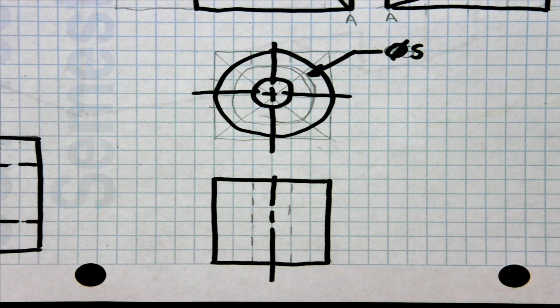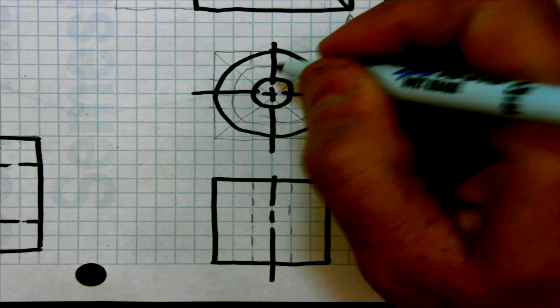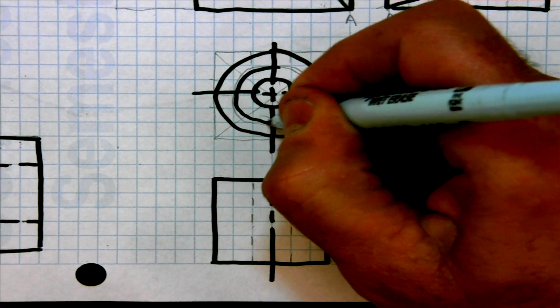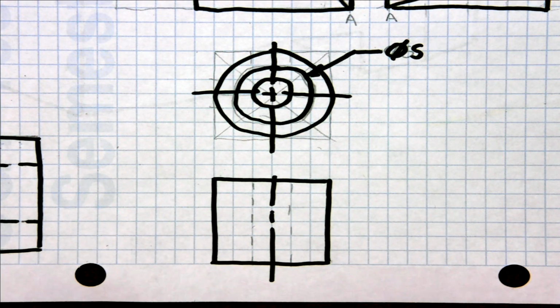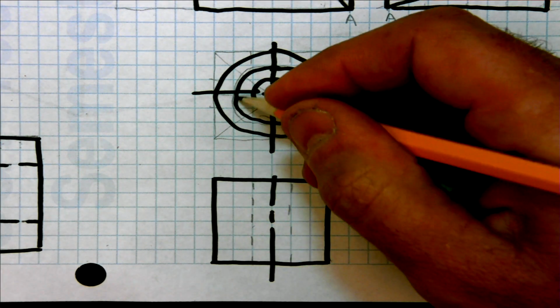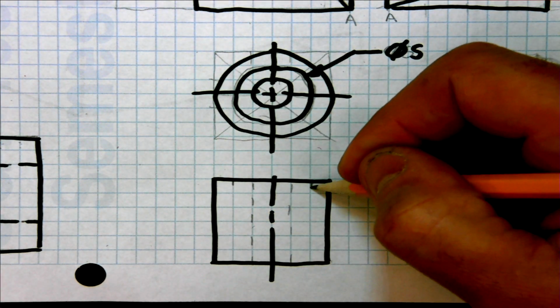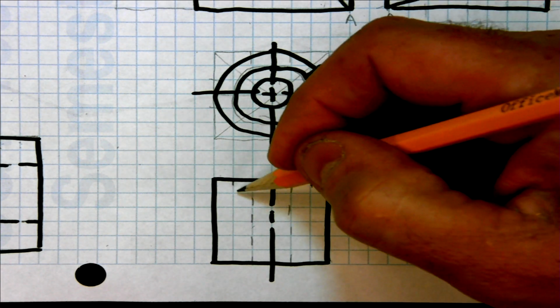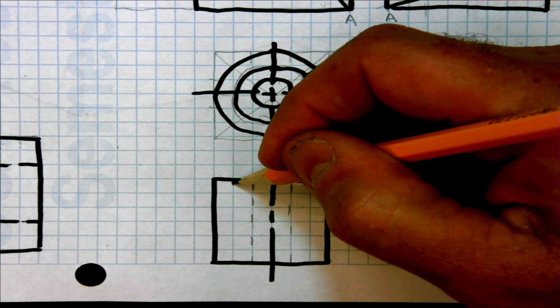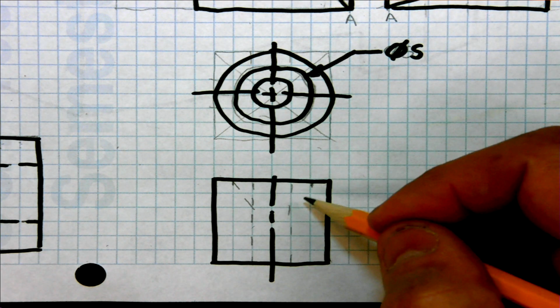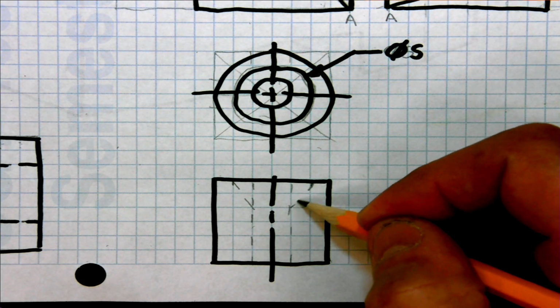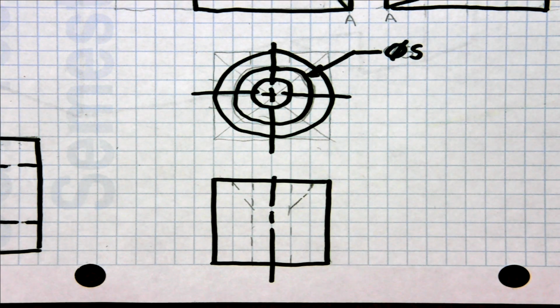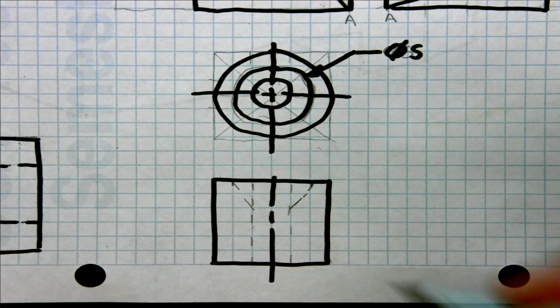But now we're going to make this thing into a countersunk hole. So again, putting my other outside circle in here. Now the countersunk hole is conical. So projecting this down here, projecting this down here, and then you could say, okay, let's just say it goes down from here to there, and then from up there to there. So darken this in.